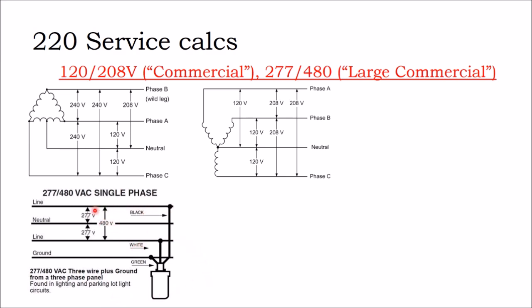Maybe these parking lot lights don't use a lot of power, but you're going over a longer distance. So what might not work at 208 volts, maybe they need a little bit higher voltage per leg just so that they can get further out into the parking lot. So that alone might drive a custom transformer type. And we see National Electric Code trying to rein it in by just saying these are the standard transformers that we use. You may go into a different country and they're on a completely different standard.